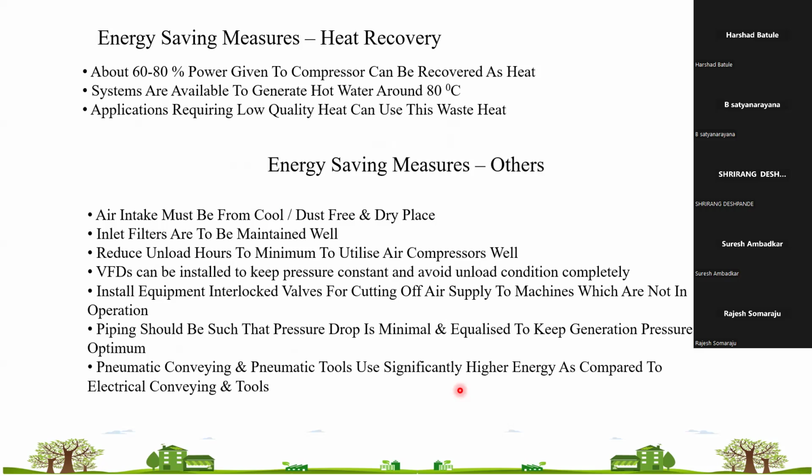There are multiple stages; in general, 5 stages of VSDs are used: 0 to 20, 20 to 40, and so on. These are the speed zones. That particular compressor will operate at different speed zones.